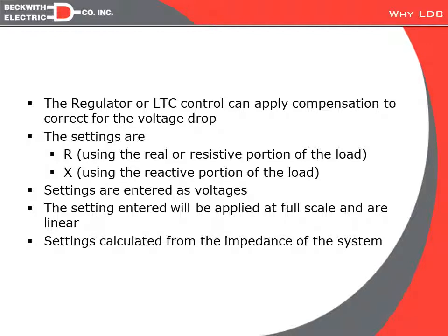So, with line drop, we have to have two portions. We have to compensate for the real and the reactive portions of the line drop. So, we have two different settings with the traditional R and X, where the R setting is going to be the real portion and the X is going to be the reactive portion.